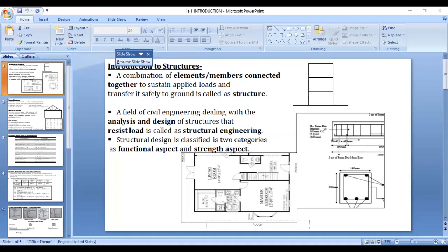If we look at the upgradation of the structure, in the concrete structure, it is very difficult to add and alter the structure, whereas in the case of a steel structure, it is very easy to upgrade and expand the structure. Then coming towards the scrap value of a structure, the concrete structure has zero scrap value, whereas compared to the concrete structure, steel structure has a large scrap value.